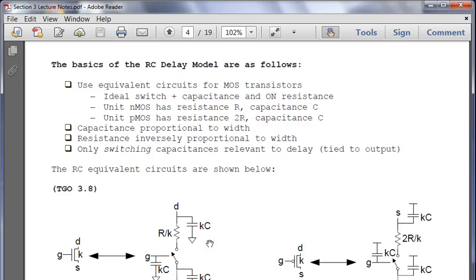So what you're going to see is that it becomes much more advantageous to use NAND gates instead of NOR gates. Because you can see a 3-input NAND gate versus a 3-input NOR gate, you start adding capacitance much faster. Just multiply it by 2 instead of multiply by 4.